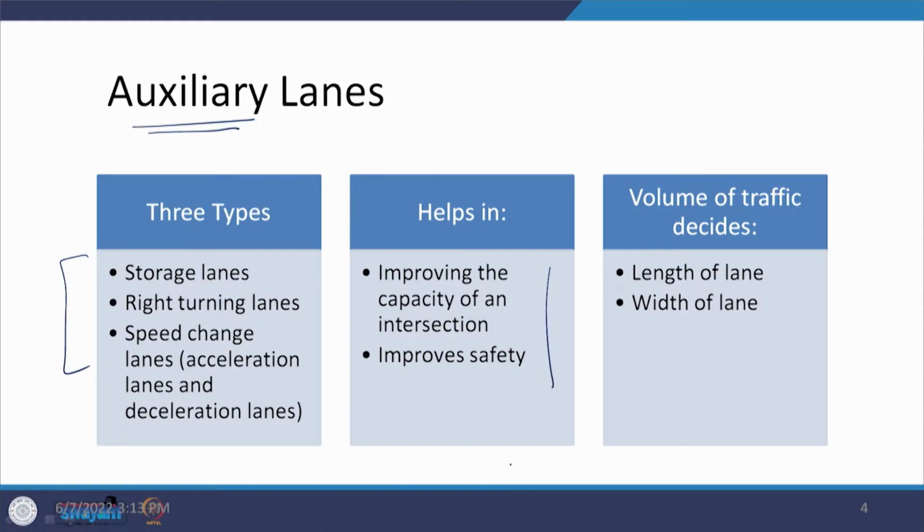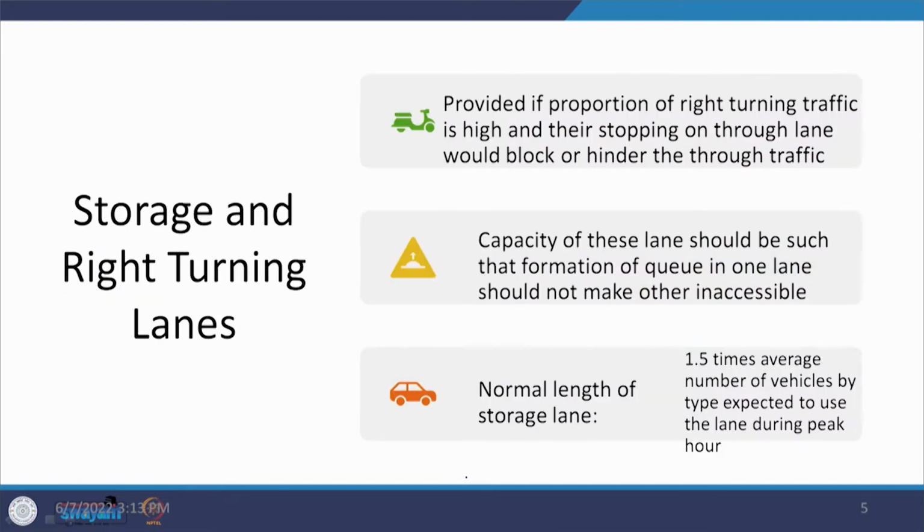But when we are looking at these lanes, when we say we have a storage lane, there is some lane being provided and there are vehicles which are moving in this lane. So, how many vehicles can come in that particular storage lane? When we say storage lane, say there is a stop line here, then how many vehicles will be there in this particular lane, and as soon as the opportunity is there to move ahead, they will start moving. So, the length of the lane is one thing, and another thing is the width of the lane. Most of the time we go with the 3.5 meter wide lane, which we have discussed from the very starting in the normal conditions. Of course, on expressways we said that it can be 3.75 meters, or on single lane roads it is different. So, the first case is a storage lane.